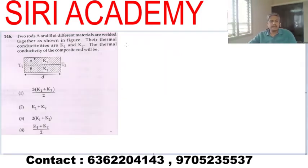This is a question from heat conduction. Question number 146. Two rods A and B of different materials are welded together as shown in the figure. Their thermal conductivities are K1 and K2. The thermal conductivity of the composite rod will be. So, two thermal resistors are connected in parallel. So, the equivalent thermal resistance is given by 1 by R1 plus 1 by R2. And thermal resistance is given by L by KA.